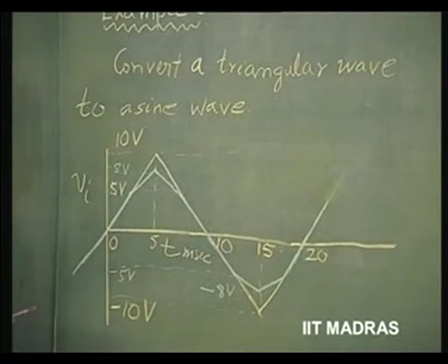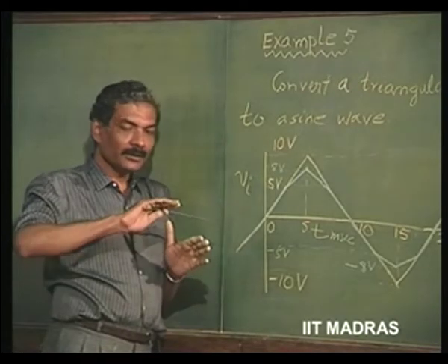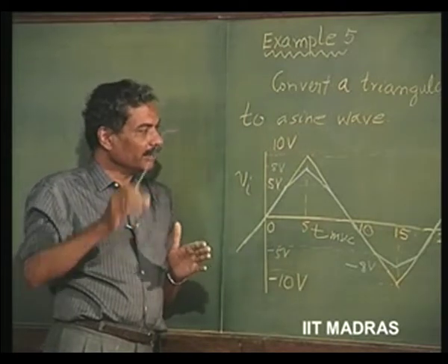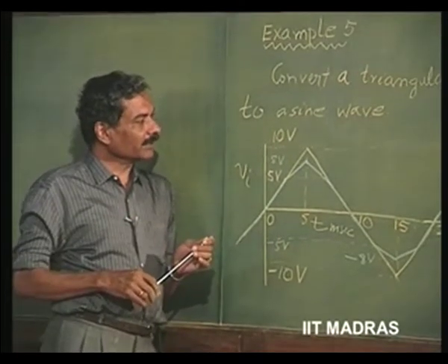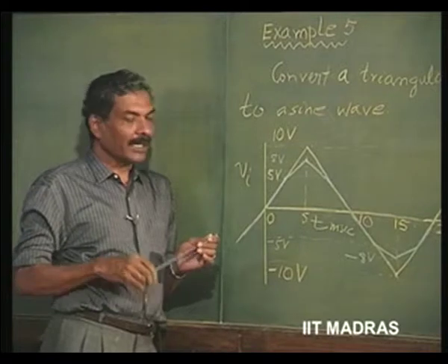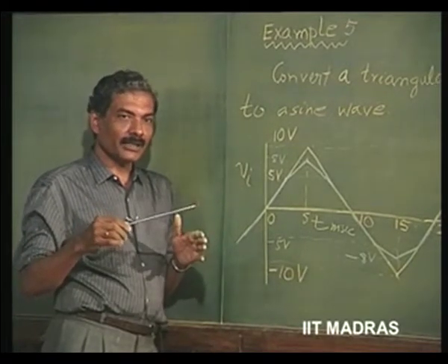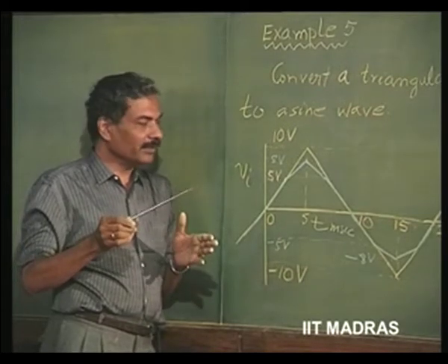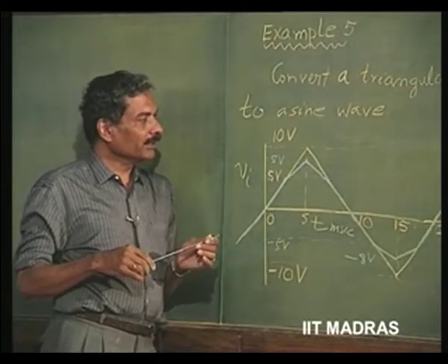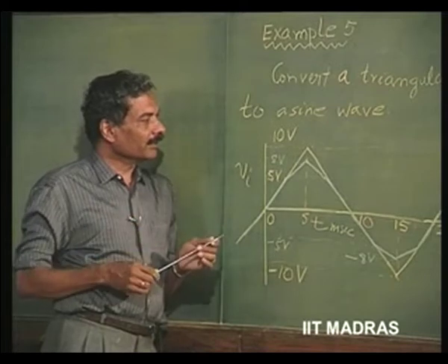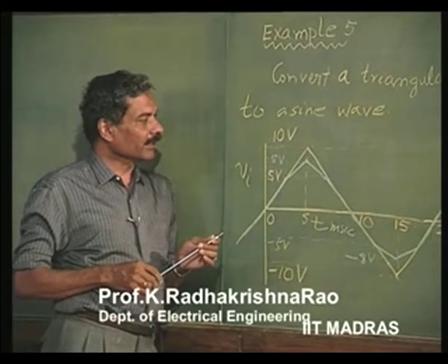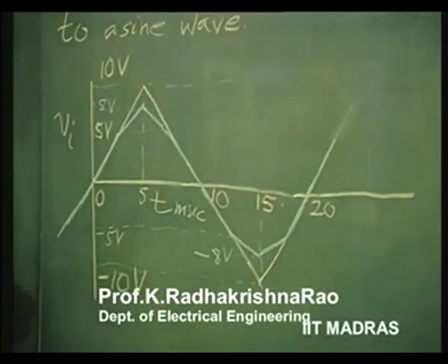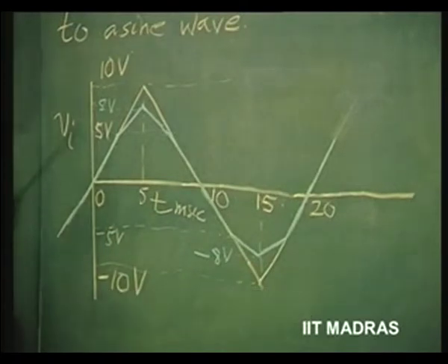So, that means you are shaping the waveform in between according to the voltage level. The transfer function is going to change. Triangle will remain a triangle up to a certain point, then it is going to get attenuated steeply by bringing in large attenuation factors, etc. This is what is going to be done by the diode transfer function generator. How are we going to do this? So, this is the application.